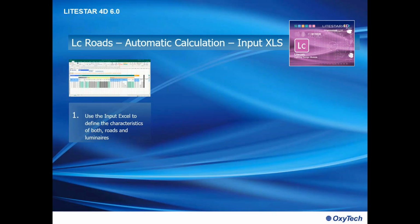So we start using an Excel file through which we can input all the information related to the roads of interest. It is also possible to define ranges. So, for example, if you want to define a range of heights of the pole, it is possible to say, okay, I want to start at 7 meters, going up to 9 meters with a step of 0.5.